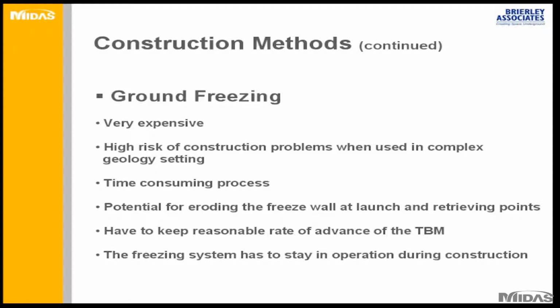When he started heating the TBM, trying to thaw the ice around the machine, he eroded the freeze wall, and the water started rushing into the shaft. In fact, the whole shaft collapsed and failed. And you have to keep this system running all the time throughout the construction process of the shaft.